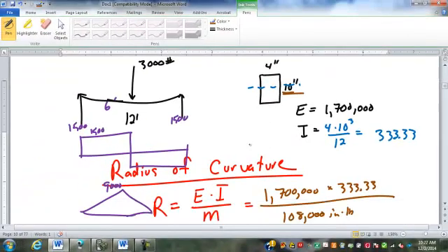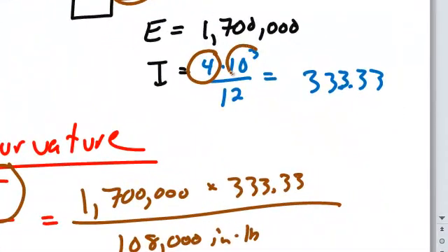In the moment of inertia, the width is in that factor once, but the depth is to the third power. So increasing the depth greatly increases the moment of inertia, while increasing the width just increases it slightly. Increasing the moment of inertia is what we need to do in order to get this beam under 0.4 of an inch of deflection.